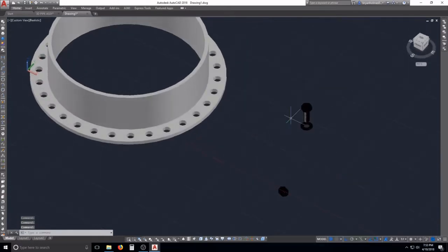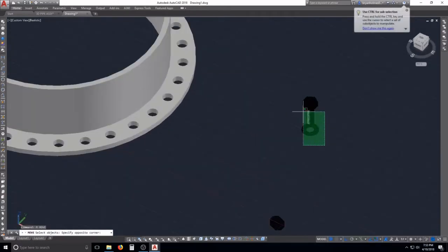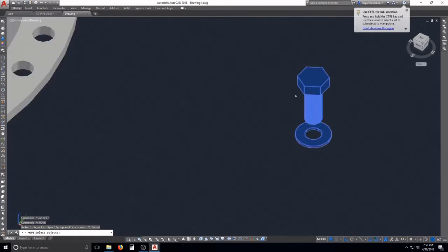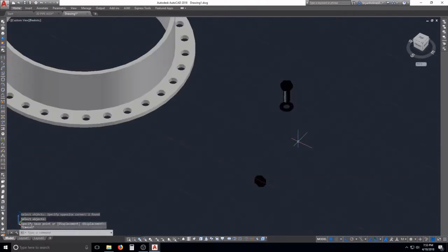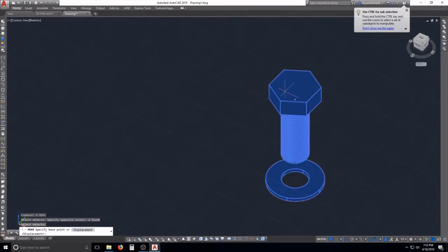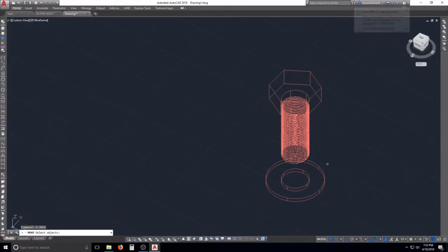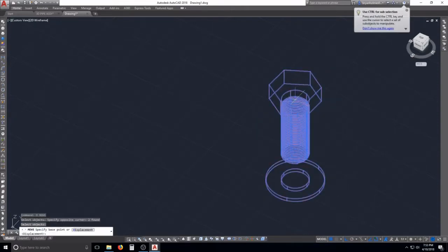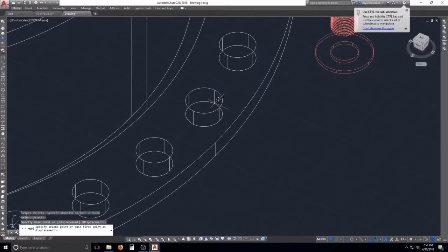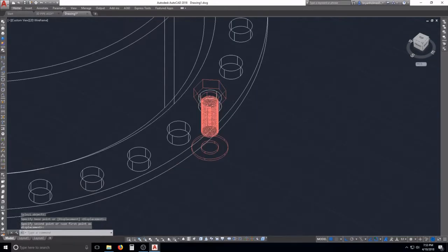So, a quick way to move these little pieces is I just typed in the move command, really. So you can type M, enter, and if you try to snap to these, and if it's not snapping, just type in CEN, for the center point. Well then, let's try to get out of the shaded. Move. There it goes. For some reason I didn't want to grab it over there. And we're just going to place it there.